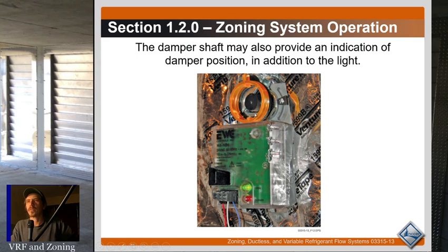So if you're ever setting one of these up, or you're working on a VAV with a shaft where you can see the actuator, stick a little black mark that's exactly in the position of the damper, so that when someone looks at that shaft, they know what position that damper is in, because that can make troubleshooting way simpler. It doesn't take much effort usually to disconnect the actuator from the shaft and feel the damper for the full closed and full open position, but it's infinitely simpler if somebody was smart enough to mark it, and most guys are.